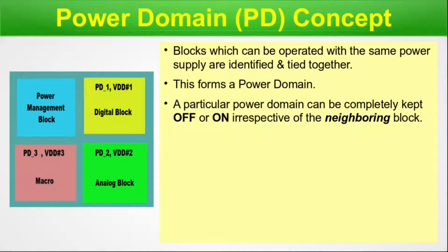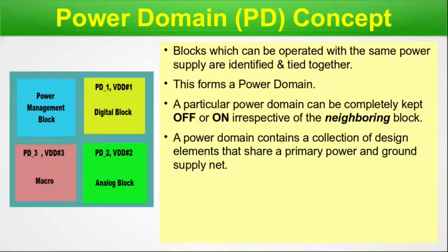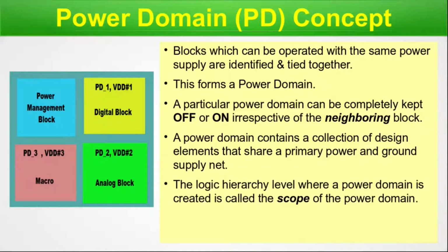A power domain contains a collection of design elements that share a primary power and ground supply net. I already discussed this verbally just a few minutes back. The logic hierarchy level where a power domain is created is called the scope of the power domain. This scope concept is very similar to the namespace concept in programming languages. So if you are familiar with the namespace concept, now you can relate to the scope. Here I have not shown any hierarchical design, but in upcoming slides I will show you the hierarchies.